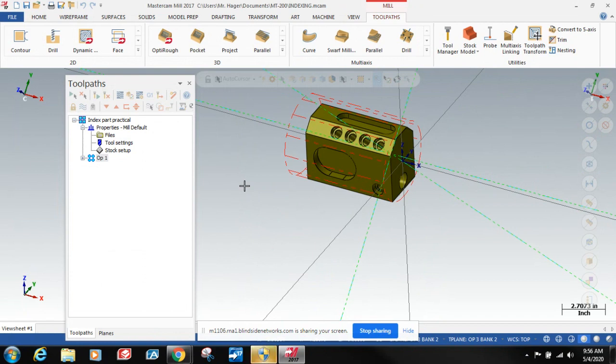I didn't even make a plane for that edge, to be honest. No, we can't do any machining on the back edge of it. We really can't do the front face of it, because we could do the side of a tool, but we can't drill the hole in it because we can't stand the part up. If we did it on a 5-axis, we could do all the sides and then stand it up. But we don't have a 5-axis, and for the 4th axis, we would have to do it as a separate operation in a vise.